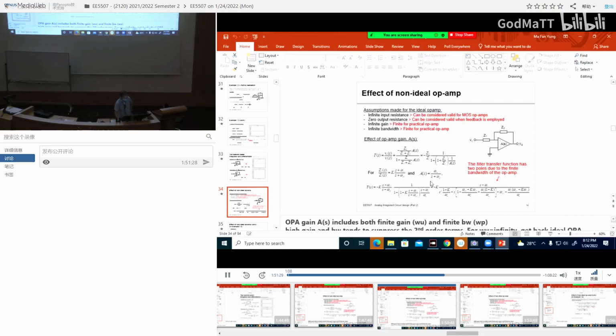Okay? So sometimes people also write differently. They just write, instead of omega u, they just put A0 or whatever. Right? A0 divided by S plus omega p. So it's the same thing. So the gain A0 is omega u divided by omega p. Alright? So now if you go and do all this, right?